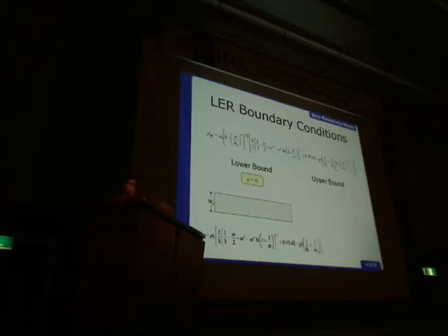So that's one check. Also, you can see where line edge roughness comes into play. Here you have this added component, which is going to impact the result. Line edge roughness is going to be strongly impacted by the sidewall scattering component, and additionally the overall effective resistivity, compared to down here, the original equation.